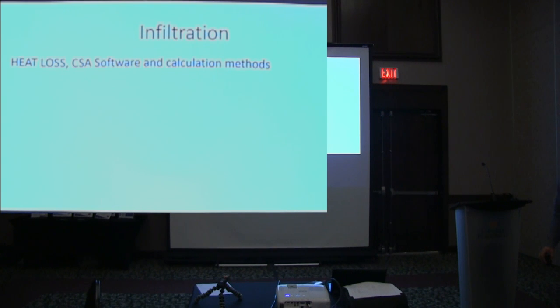Can we use fireplaces in the new method as the heating appliances for the house? Yeah, you can specify additional loads if you know what that fireplace is putting out. But the BC building code does require adequate heat in every room to match the loss of that room. So a single central appliance would not meet the requirements of room-by-room distribution that the code calls for elsewhere. In other words, if you're putting in baseboard, radiant floor, forced air or whatever, every room that has a loss needs heat.